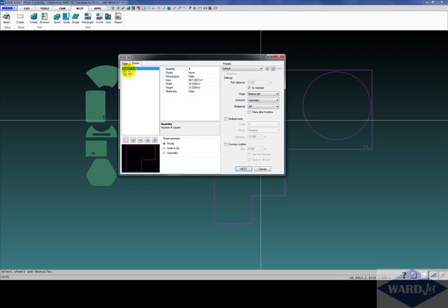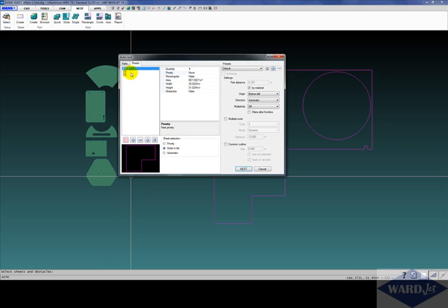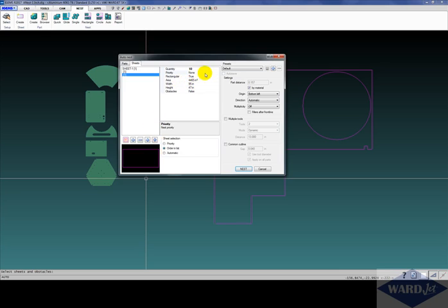That's available sheets. And similar to the parts, you can also specify a priority. So if you definitely wanted this sheet to be used first, you can set this priority to highest. The other option is down here. You can specify to go by priority or by the order list, or automatic. It'll just find the optimum material utilization. So I can just set this to none, and as long as this is first on the list, I select order in list here, then it'll use this first, and then this, and then it'll start working through the 10 sheets that are available of this material.